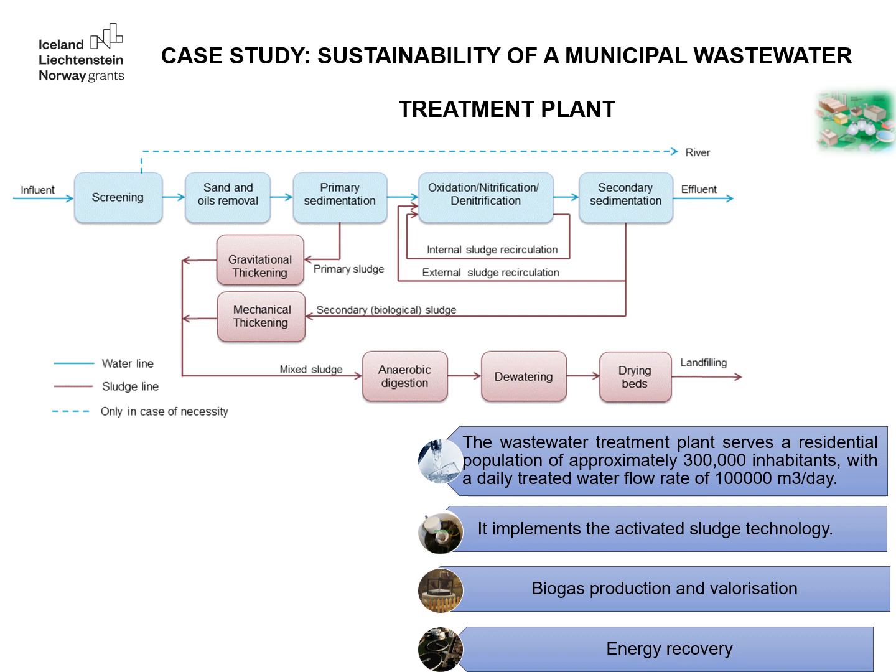The mentioned wastewater treatment plant has a complex structure and utilizes various stages and technologies to treat wastewater and to remove the pollutants. Pre-treatment stage. This stage is used to remove larger impurities such as solid waste, sand, and other sedimentable material. This helps prevent clogging and damage to equipment in subsequent treatment stages.